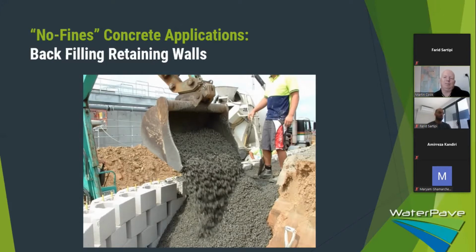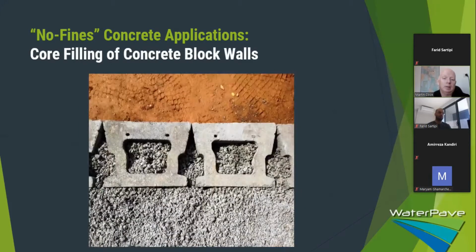That's exactly what no fines concrete was designed for, to backfill behind retaining walls, and it's the best way to remove hydraulic water pushing against the retaining walls. You can see there that that's exactly what it's used for, backfilling behind the retaining walls and core filling the block walls.